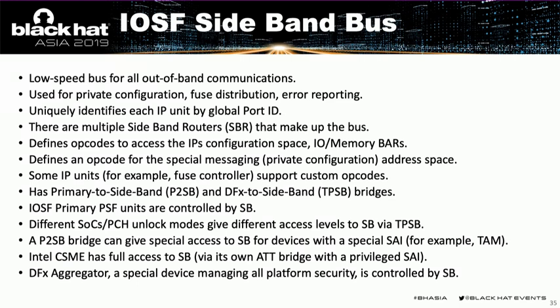We also found that the Intel Management Engine has a very privileged bridge to the IOSF sideband bus. So the Management Engine has full access to the sideband bus and can control all hardware of the PCH.